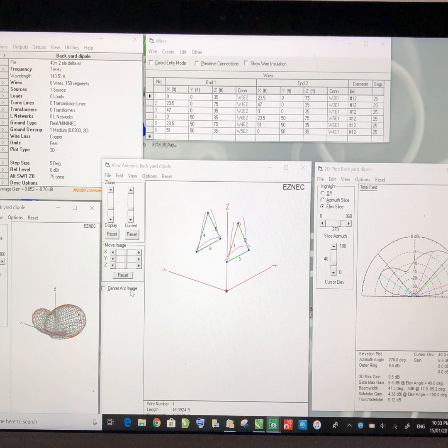You don't have to solder those connections. Sometimes for various antennas I've used electrical connectors, heavy-duty electrical connectors with a screw-down clamp, and providing they're well insulated, well taped up at the end, then these work quite well.